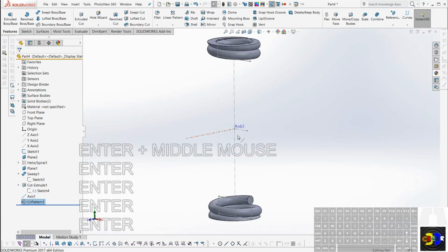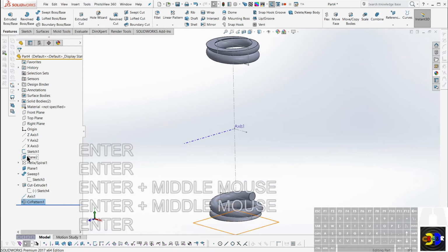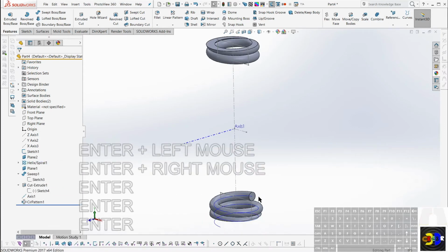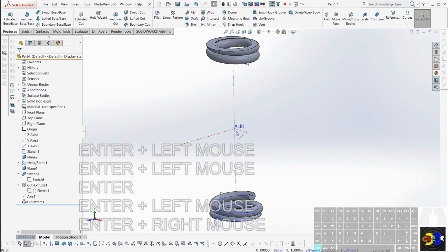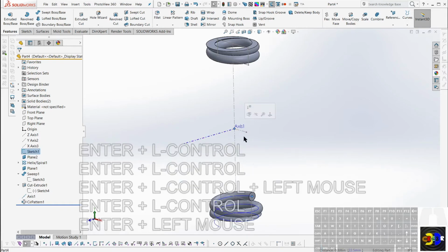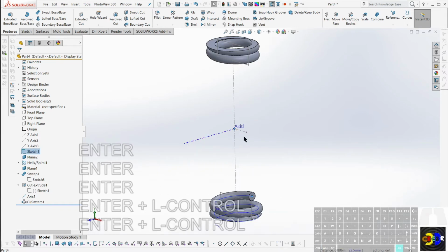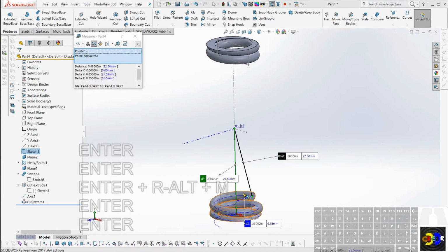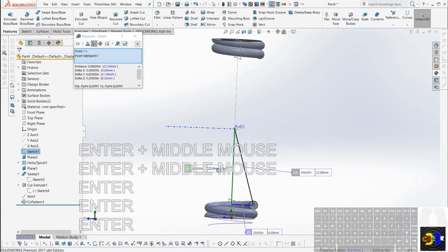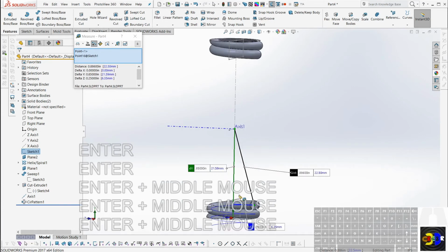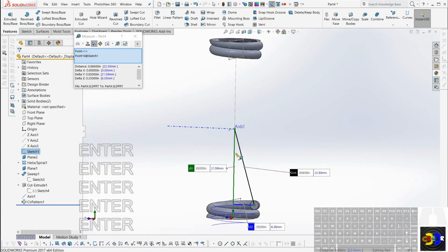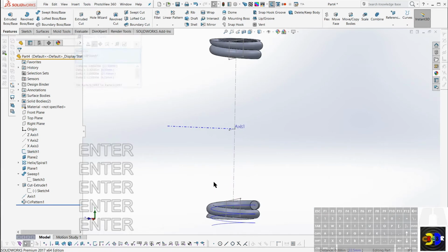So I want to show my path again, so I can select this endpoint, and this is halfway, and if I say Alt M will measure, and that is just in the Y direction. The Y component is 0.85 inches, and so my overall helix length will be twice that, so that will be 1.7 inches.